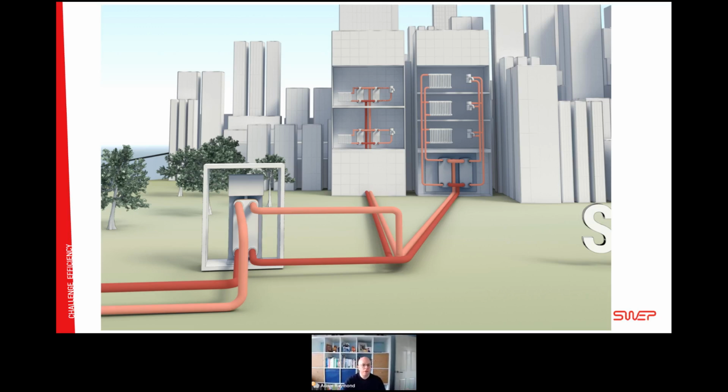The benefits here are that we get hydraulic separation at the apartment level. There have been some concerns in the UK market about leaks if it's a different type of system, if it's direct, as we see here on the right hand side. If you can imagine a leak occurring in the pipework in this apartment, it is going to cause problems. So this is not where a two-stage solution would be used.